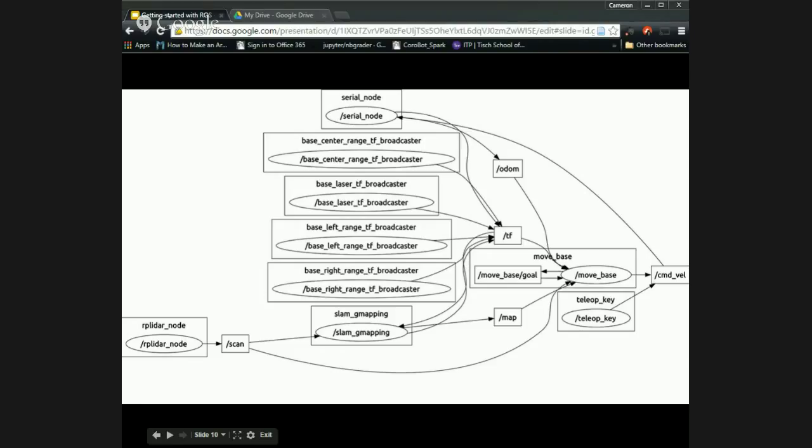We talked about the components of ROS, the key concepts, first of which is ROS being a distributed system that allows you to run applications across multiple machines. That's how the new Corobot ROS stack, which we will be announcing when we ship the first updated units of the CL4, is designed: your higher level applications run on a desktop workstation, and the robot is just a data acquisition system that streams data back. This provides a lot of advantages in optimizing the power and performance of your robot system.